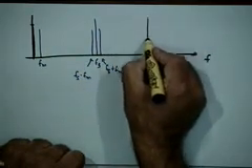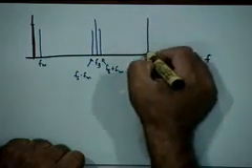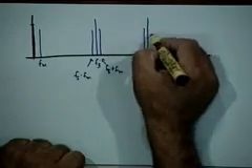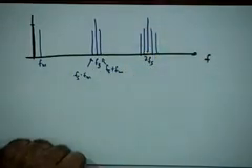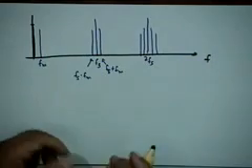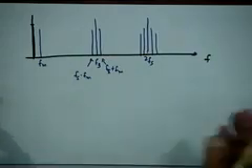And then you have components around 2 fs, and these amplitudes will be different, and so on. But there can be additional terms here. Just like we have many components in an FM signal, rather than only the two sidebands, we have many components here around fs, 2 fs, 3 fs, and so on, not just plus fm and minus fm.